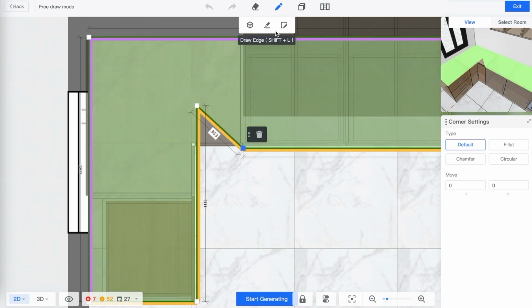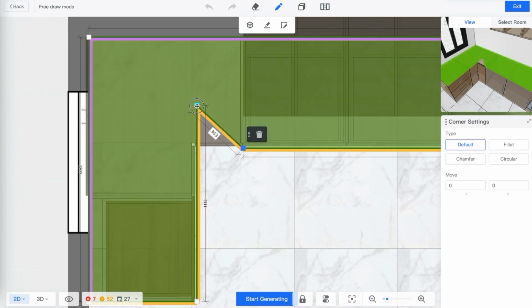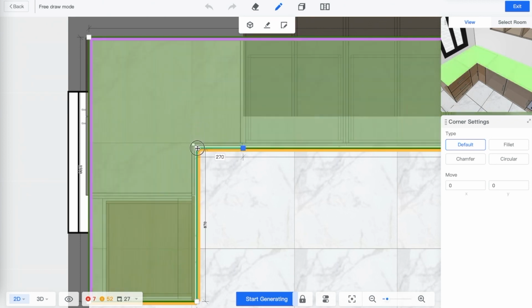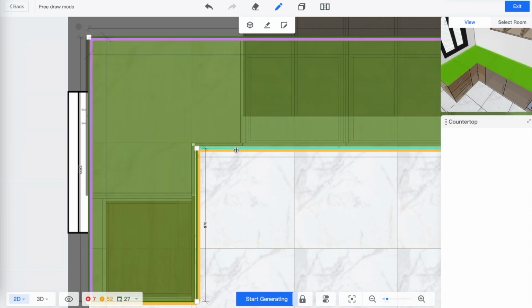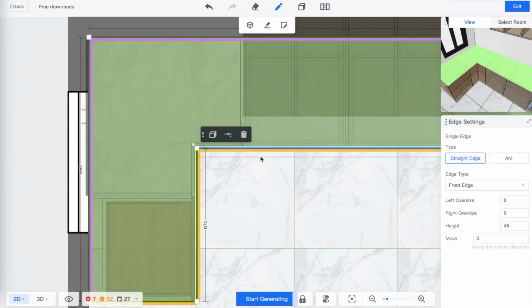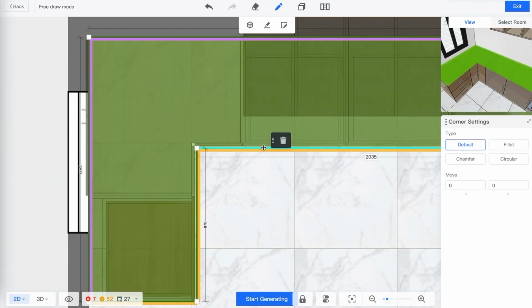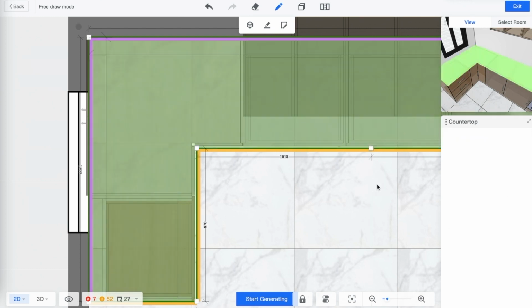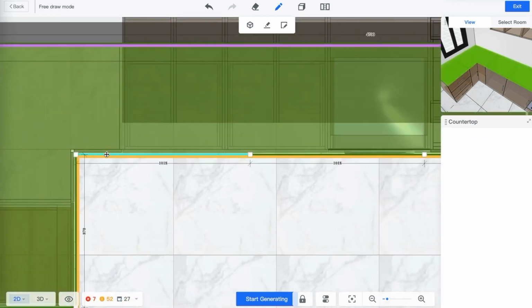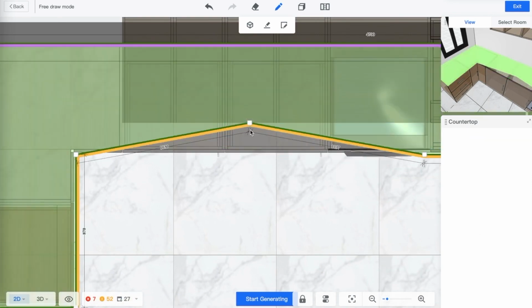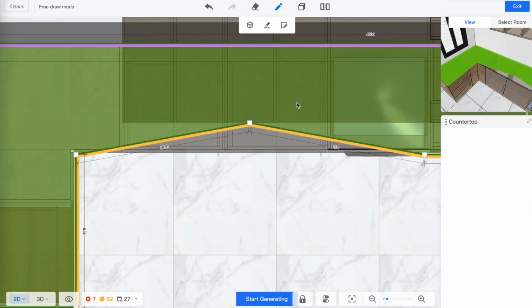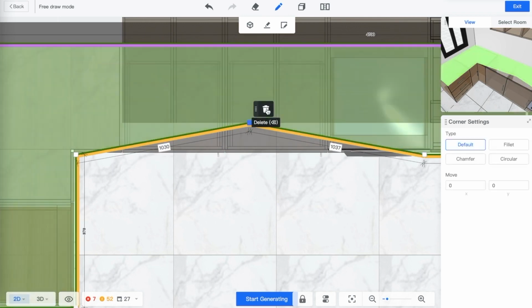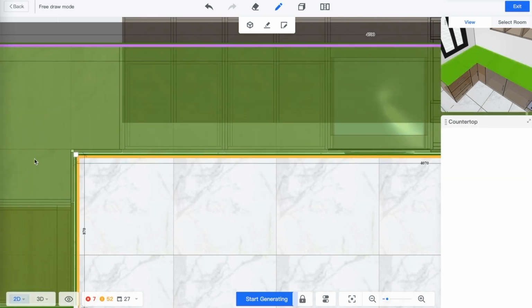You can either drag it down until you see the color line is perfectly vertical, and hit delete. And you'll say, what if I want to add more points? It's very simple. Once you click on the line, you can add a breakpoint anywhere you want. Add another breakpoint. See? And then once you click on the line again, you'll be able to adjust the angle, if you need to do this adjustment. Here I'm not going to do that. I'm just going to delete this breakpoint.